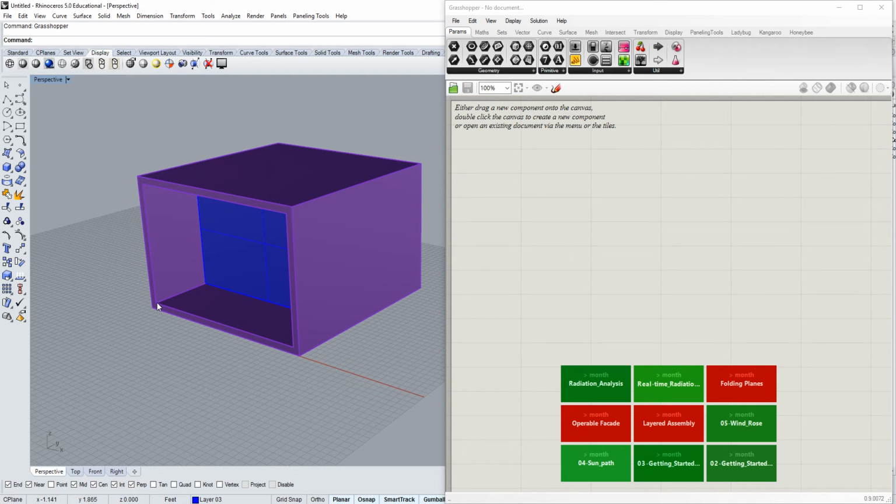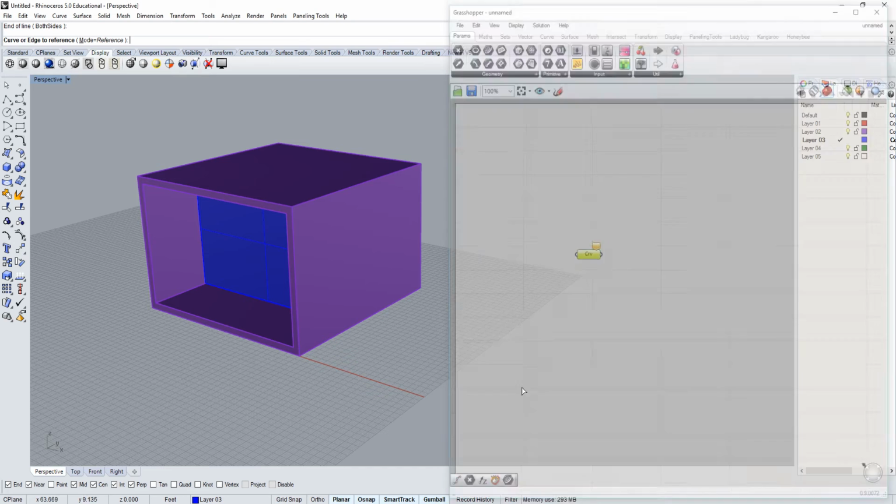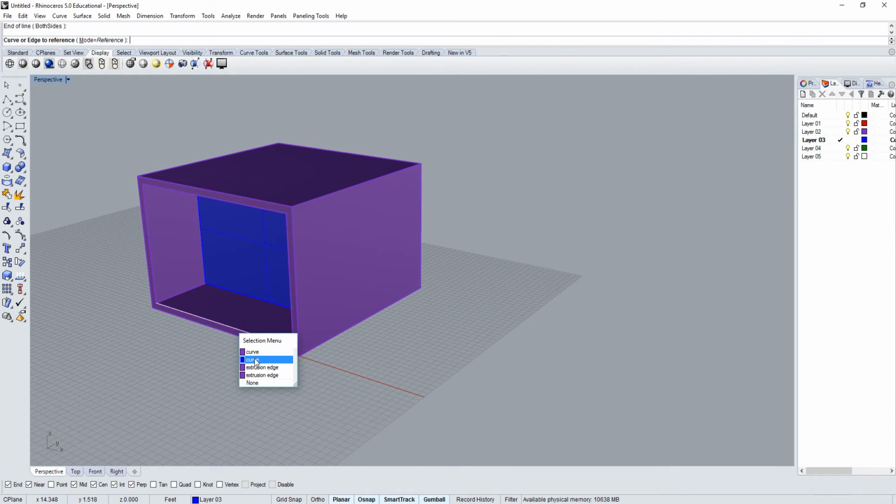And so I'm going to place a curve along the edge that I can reference in order to model off of. So I'll go here to curve. And I'll have to actually model one in. So let me go to line, and I'll draw a line from here to here. You probably won't see it there at first, but set one curve and set it to this curve right here.